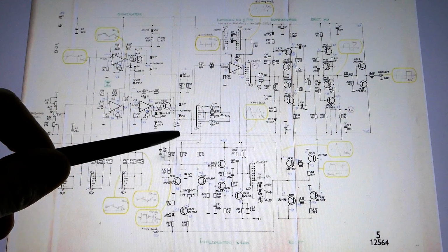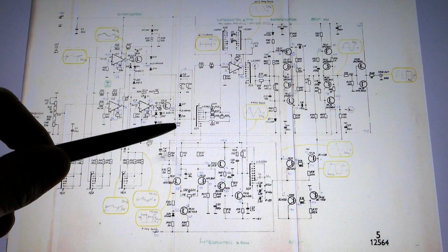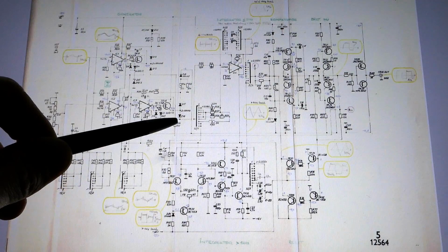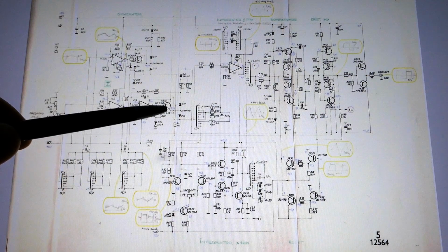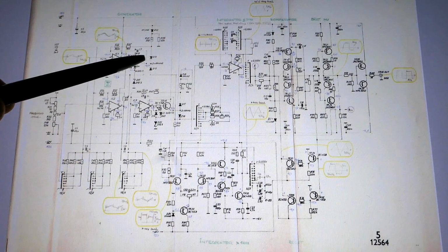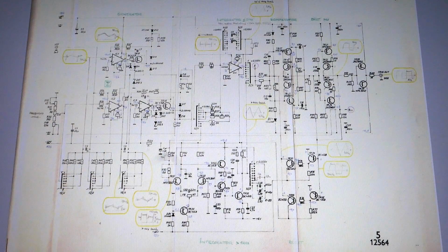Of course, the lower the feedback voltage is pulled, the lower the frequency. And it has to pull the voltage down after this resistor in both polarities, in both half cycles, and the negative half cycle is pulled up to a lower negative level using this NPN transistor, and the positive half cycle is pulled down to a lower level using this PNP transistor. And these transistors are controlled using these op-amps, and they are somehow connected to this frequency control potentiometer, which basically just controls a voltage. There is no AC on this potentiometer.